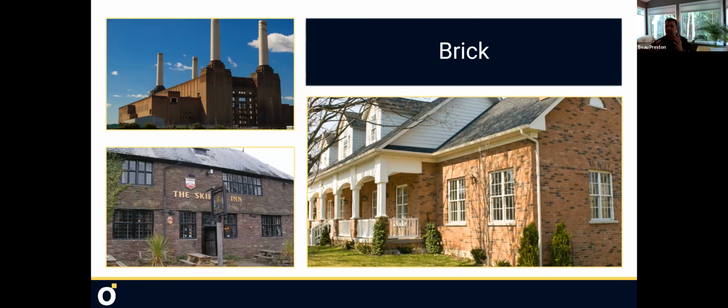What did they lose? I'm not saying, don't get me wrong, brick is a sustainable product. It's just further down that spectrum. They gained efficiency, so they lost a little bit of lifespan, right? So stone is the pinnacle. Brick is a man-made stone. It's an engineered stone. And now they get efflorescence. They get more of a reservoir wall, meaning they're absorbing moisture, whereas stone would often get rid of the moisture. Certain stones will absorb moisture, but not the ones that we purposefully put in the wall a lot of times. So you follow, we're just following a little further down the spectrum, gaining efficiency, losing sustainability.